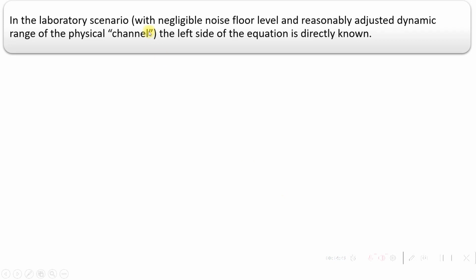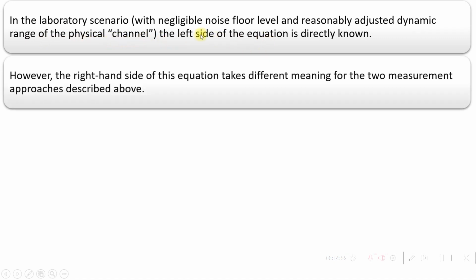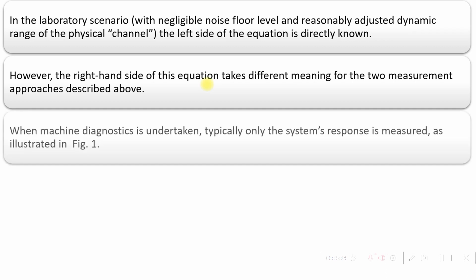Now, in the laboratory scenario, with negligible noise floor level and properly adjusted dynamic range of the physical channel, the left side of the equation is directly known. However, the right hand side of this equation, the response equation, response is equal to force into frequency response function, takes different meaning for the two measurement approaches I have already shown you.